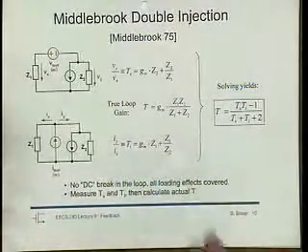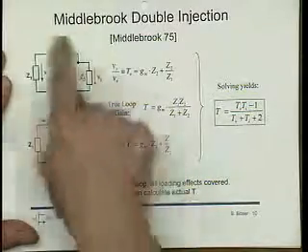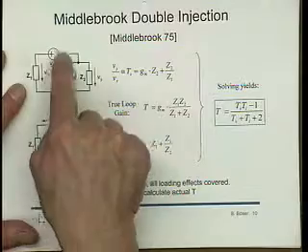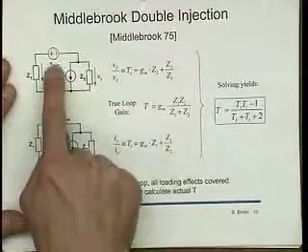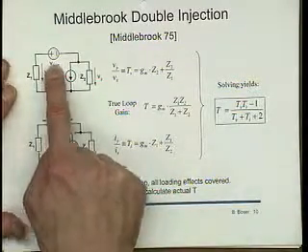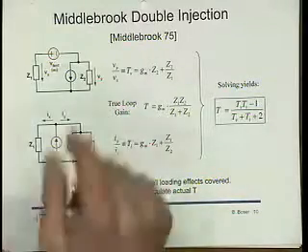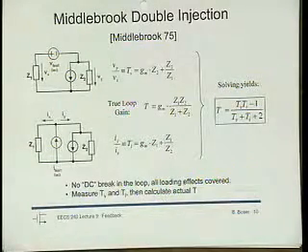Anyways, the point is that we take our circuit and we first drive it with a test signal. That's a voltage source, which will have DC-wise 0 volts, so it's just a short. We certainly haven't changed our circuit at all by inserting this voltage source.